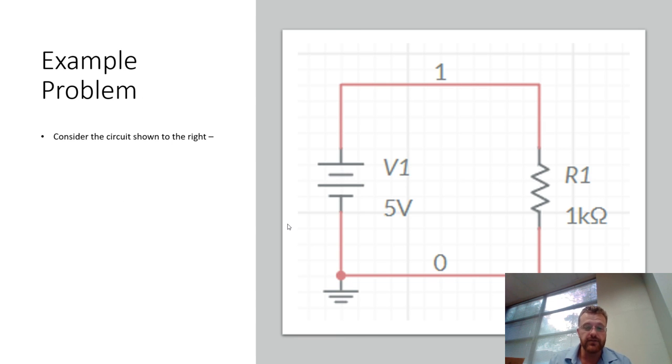So let's think about how we can actually do basic circuit analysis applying Ohm's law. This is the first really complete circuit we've seen. We have an ideal voltage source, which has a rated value of 5 volts. We have a resistor. There's that schematic symbol we saw on the previous slide. Note that its rated value is 1 K. This K is just kilo, right? That's a metric prefix for 1,000. And this is the capital Greek letter omega. So this is just 1,000 ohms.